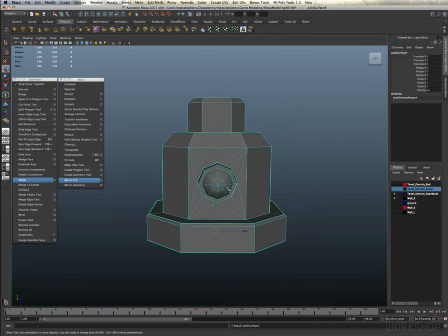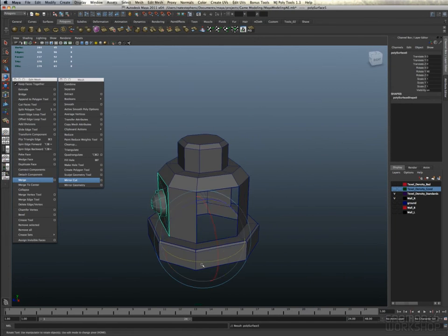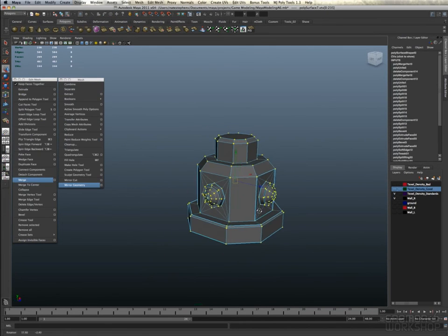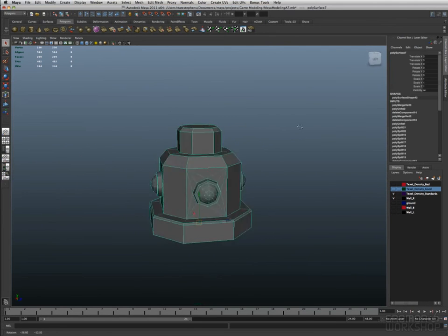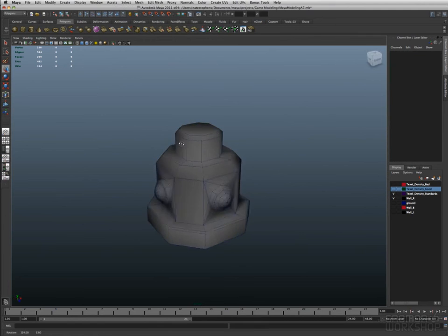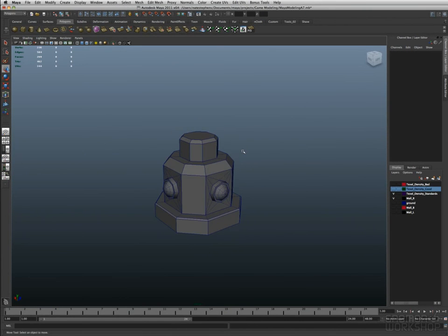And to duplicate what we did with the circle and this front face, I'm going to extract that face and now rotate it and put it back on and combine the object so that I don't have to do that work 4 separate times. And there you go. We've created a nice little element just with the tools that we learned in this chapter. I'm going to go ahead and soften the edge and then harden it back just to make sure that everything's welded together. And there you have it.